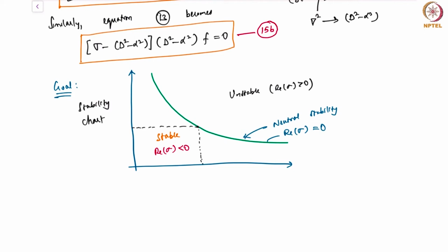There's one single control parameter which you, as a user, have control in varying, and then you examine what is happening to the stability of the system. Now if you're on one side of the stability boundary, let's say over here, in the stable region, you could have two possibilities. You could have a purely damped non-oscillatory solution, or you can have a damped oscillatory solution.